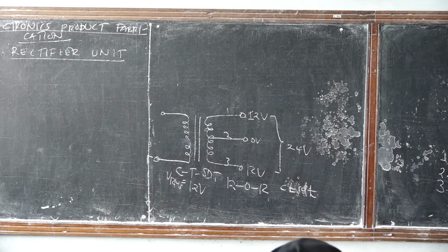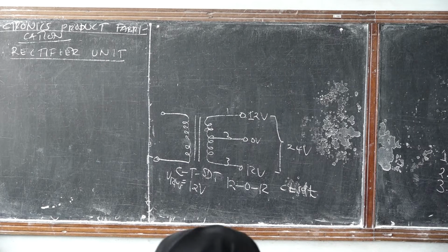So the transformer matters in your design of a linear power supply. The challenge we have, especially in your institution, is that students are not careful in the choice of the transformer. Especially if the system you are going to power draws a large amount of current, so large amounts of power, then you can find that you are doing all of your designing, and when you try to test it, the power supply is not working at all.